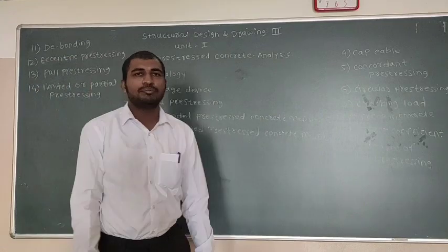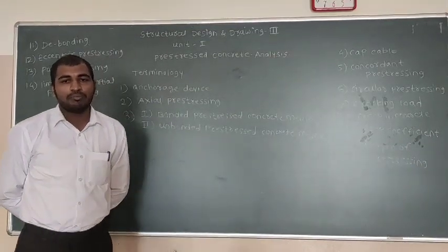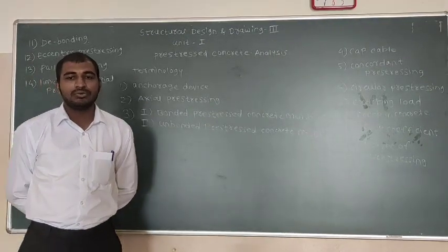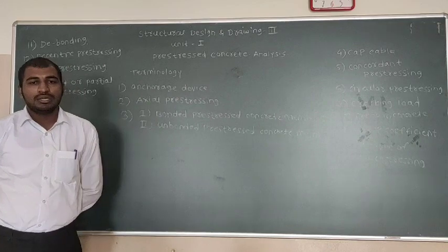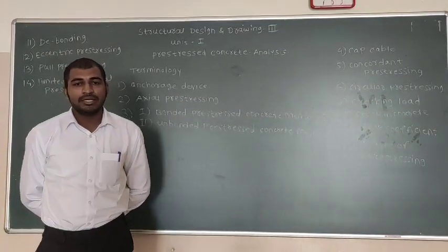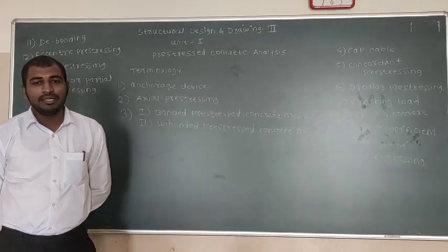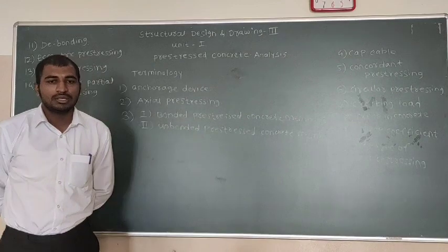Limited or partial prestressing is the degree of prestress applied to concrete in which tensile stresses of limited degree are permitted in concrete under working load.